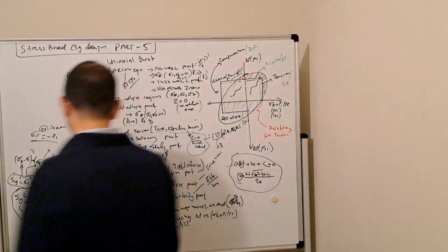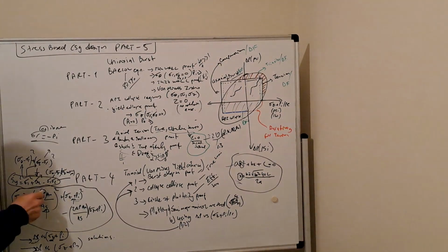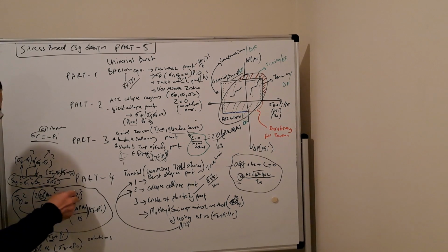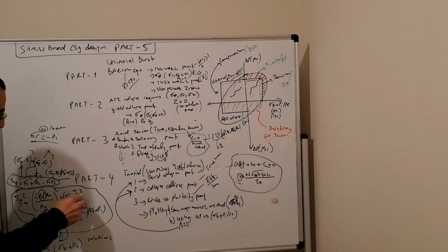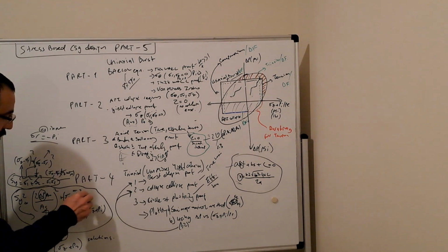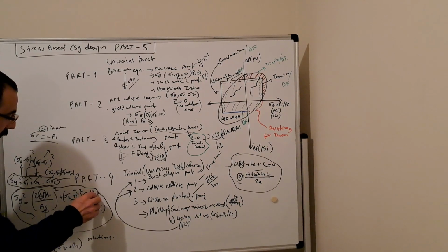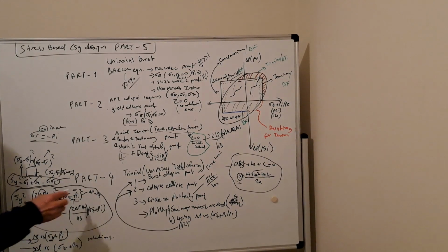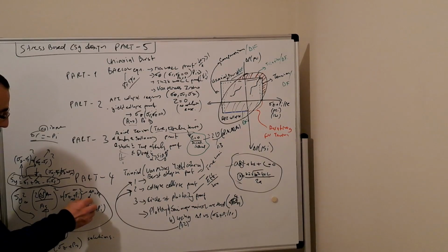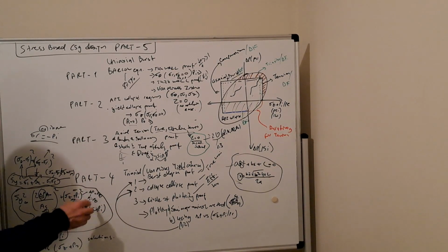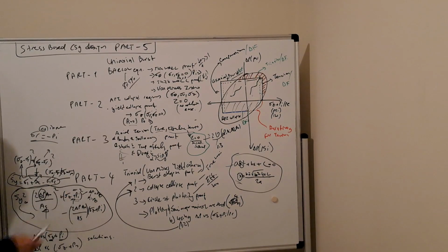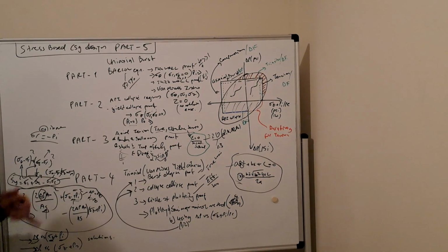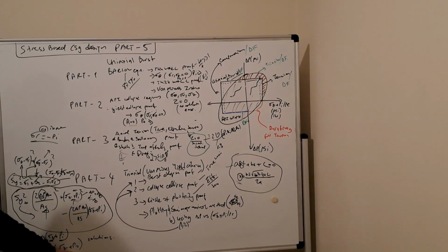Also, on the second one, we wrote the pi in the version of delta p plus the pe, because we know that delta p is pi minus p external. So we wrote this equation, and found the other equivalent, delta p versus axial stress plus the external pressure.